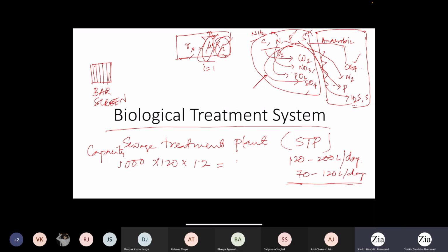The wastewater will also have a lot of floating materials like floating bottles, plastic bottles, or different polythenes or bigger substances. Now, to get rid of all bigger material or floating material, first you have a bar screen having certain gap. So this screen aperture size will be a little bit bigger to arrest all bigger floating particles or bigger floating material like bottles or polythenes or any other bigger substances.